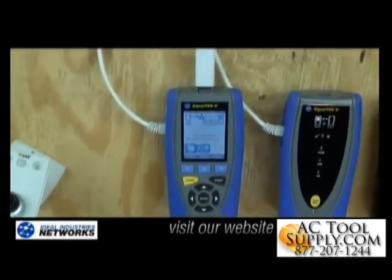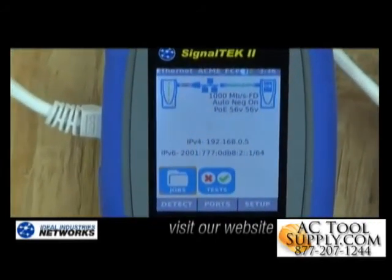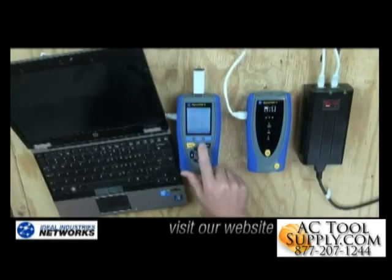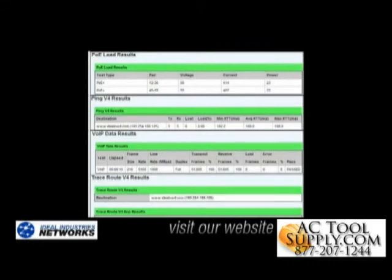The SIGNALTEK 2 tester will also track and organize your test data by job and test location, and those results are easily downloaded, viewed, and printed via a web browser. Those reports provide a basic pass-fail summary, as well as an individual test result per cable. And I can use those reports for as-built documentation as I'm installing this system, and for a reference for troubleshooting events somewhere down the road.